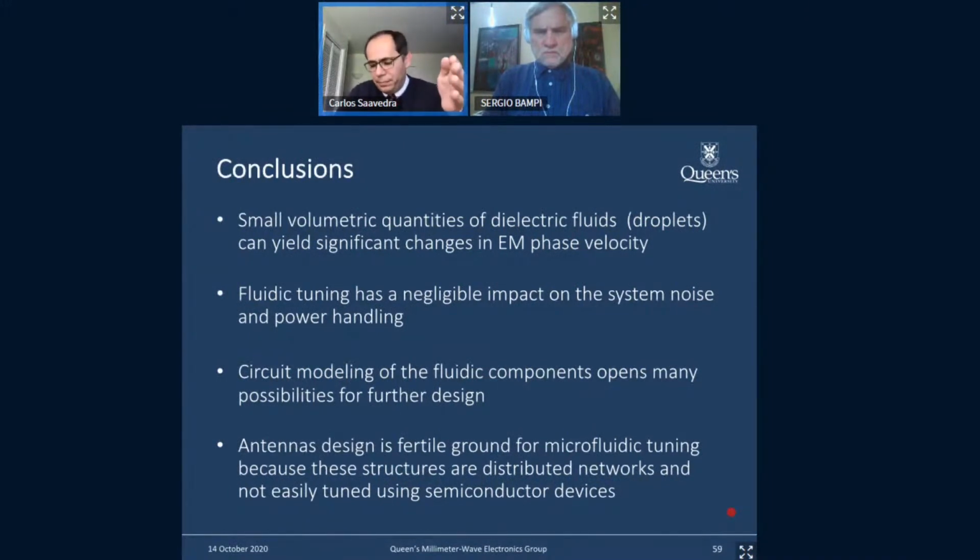So that actually, Sergio, is what motivated my group to take a detailed characterization and a study of the dielectric frequency response of a number of fluids, because that really hadn't been done systematically for a lot of the fluids that we're interested in for this type of RF design. We've published that data now, it's out there. So in the future, if I were to design another filter, I would not use that particular compound. Now I know pretty well that certain oils have much less loss over a wide frequency band. So it depends on what you're going to use.